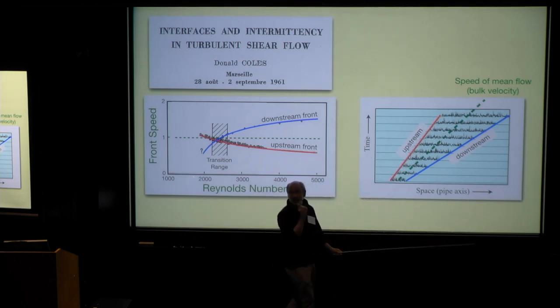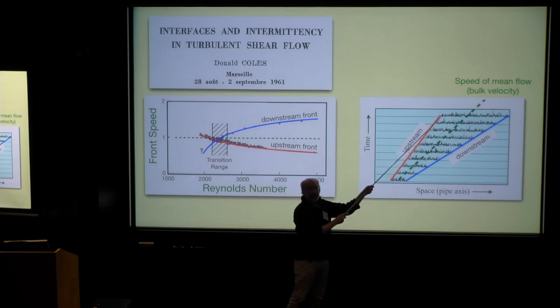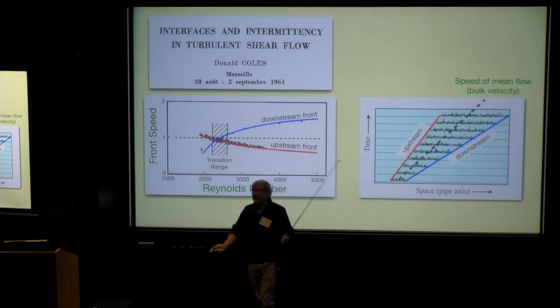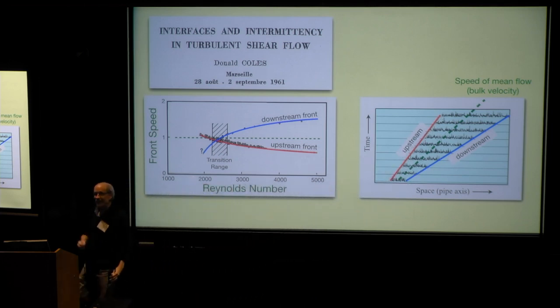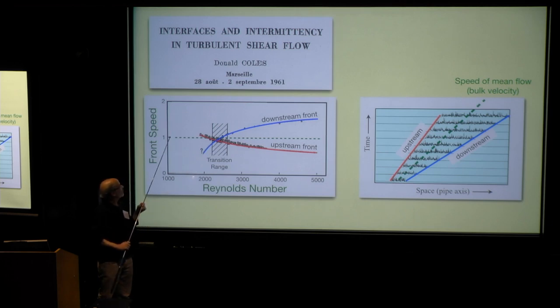and so this upstream front is propagating against the headwind. And that is really important because, just to be clear, you have entrainment of turbulence. Laminar flow is being entrained into turbulence here, okay? It's just an artifact that it's going downstream. There's a conversion of laminar flow to turbulence there, and it's really key to what is going on. We can understand all this. I won't explain the full thing, but the fact that these come together but below the mean speed is significant, and so on.